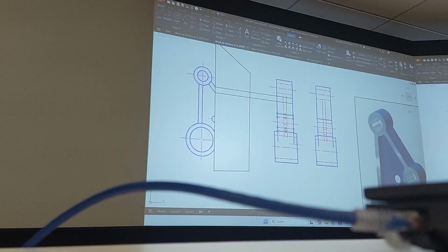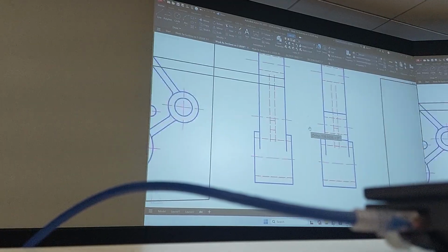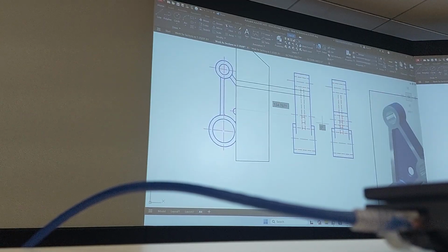See how visual that is? So I'm going to just delete those. Anything to the right of the section line we don't need, so I delete that. Now I can go across. So right here is the hole. Here's the hole. You see it cuts through that dashed line, or this red line here.